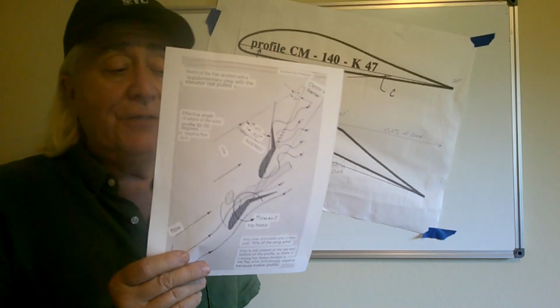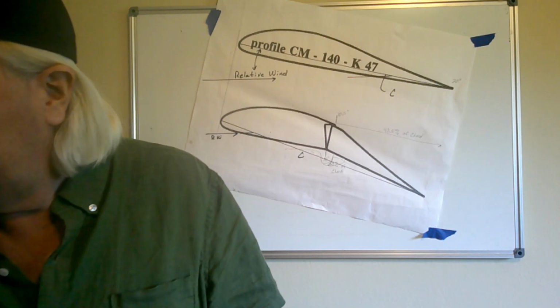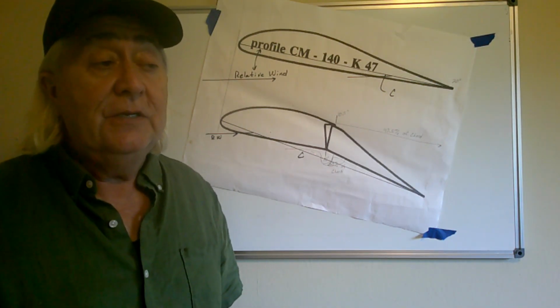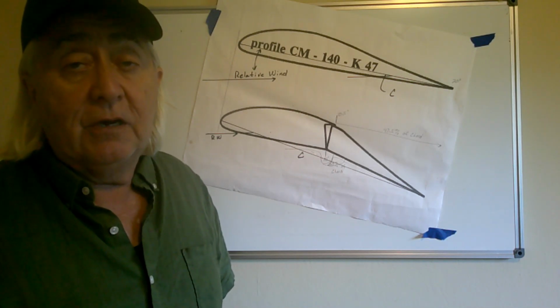It's the thing that happened first, and put it into a configuration somewhat like this. And maybe the flow separated off the elevon, maybe it didn't. Was it the huge flap overpowering the elevons? Well, that's what made it difficult to trim up front. It's not what caused the stall.